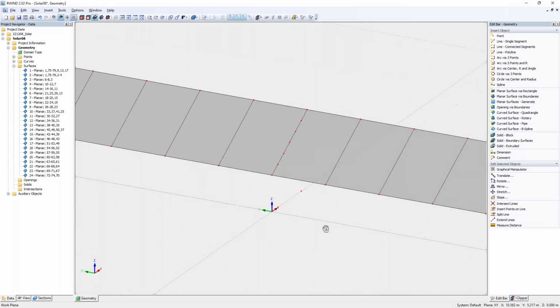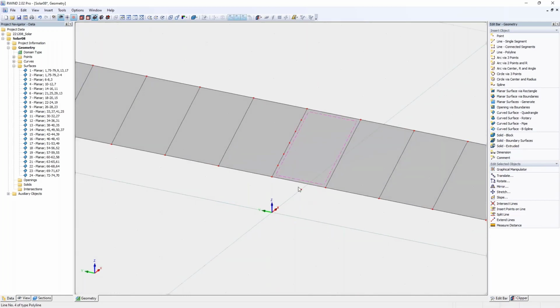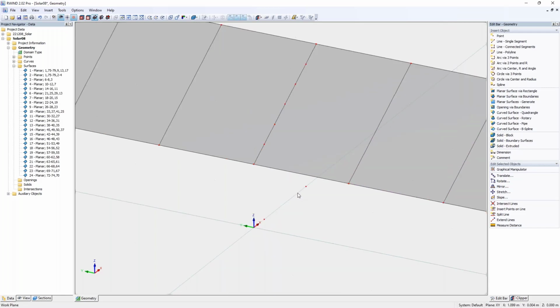You can imagine there are smarter ways or even faster ways, but I'm usually used to doing some quick geometric stuff. And then I want to have quite thick columns, just for an example, 20 times 20 centimeter columns. I will use this, press Ctrl C and Ctrl V on my keyboard, which is quicker, most likely, than the translate, but the translate offers some more options. But if you just want to quickly copy some nodes, like me, I want to copy it in this direction, then I can do this because I want to create a rectangle.